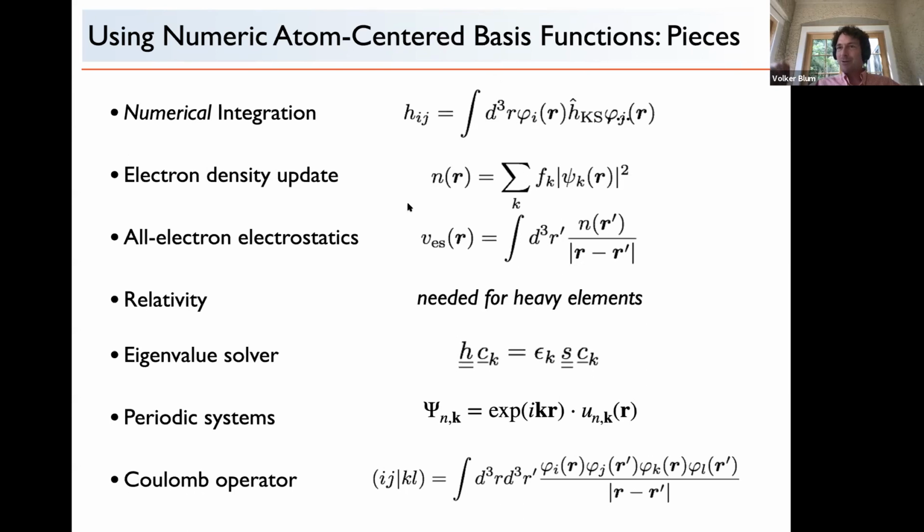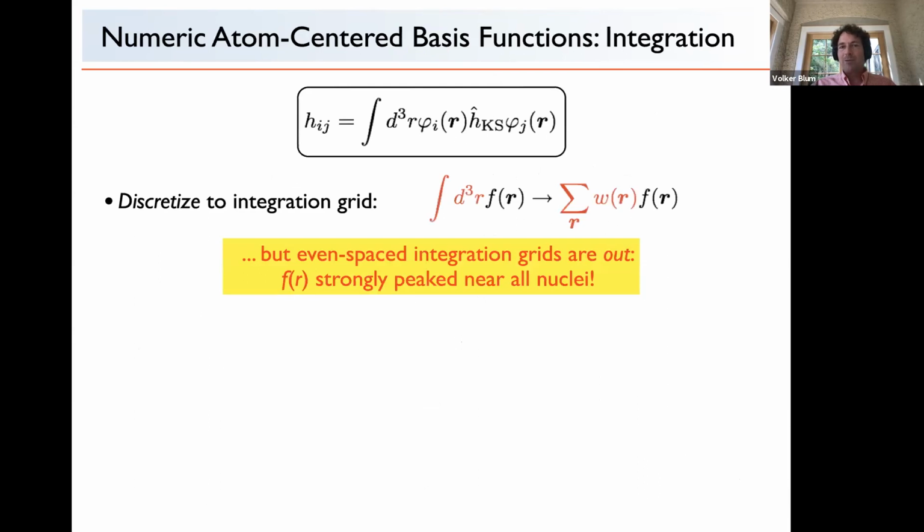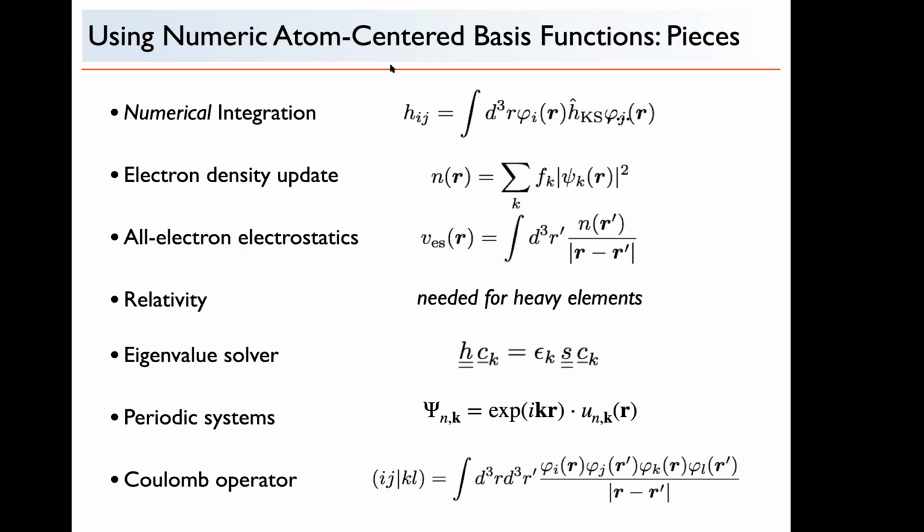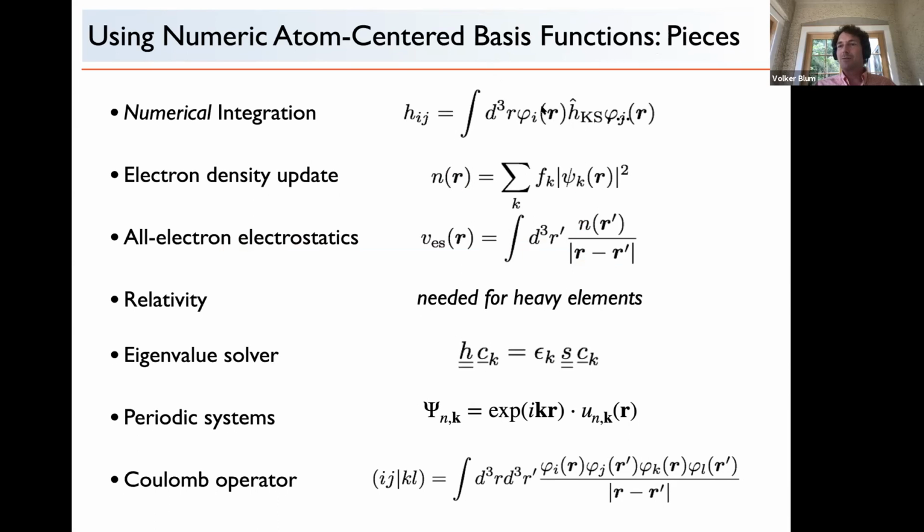Great. So how do we do this? A few more minutes. Perhaps the one thing that you'll see when you use FHI-aims in the tutorials, or if you've already used FHI-aims, is what some people consider, I've heard, unusual recently, which is that we keep our numerical defaults out in the open. We have species defaults. For instance, the grids here can be specified. You can copy a species default file into a control file. You don't need to touch it. It just has to be there, and it tells the code what precision to use.